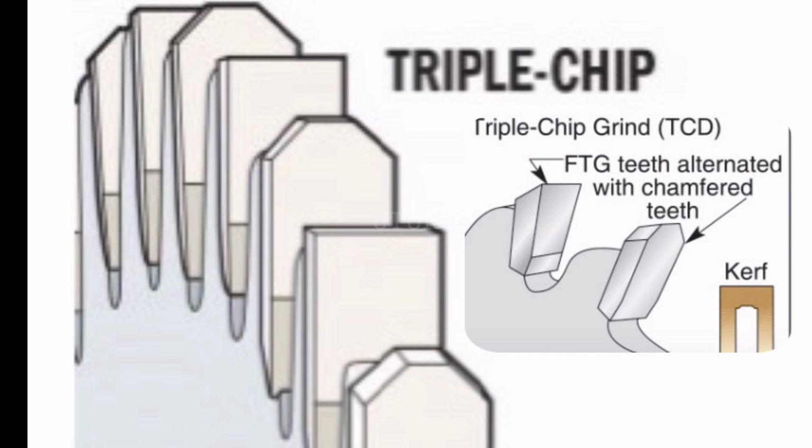The TCG geometry is particularly suited or designated for particle board products and abrasive materials, like your melamine and MDF. Melamine can be used as the litmus test or acid test in determining good quality cuts from your TCG. Suffice to say, if you get good quality cuts from your plastic or plasticized melamine, then there is a high propensity or likelihood that you will get good quality cuts of your veneered plywood using your TCG tooth geometry.